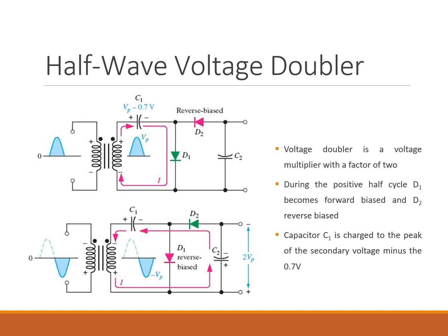Yeah, no transformer is needed. It's ideal for low current, high voltage because we're stepping up the voltage, and there's no way around it. Current has to go down if voltage goes up. It's the law of conservation of power. There's no other way, not in this universe. All right. So again, each half cycle builds up to the output voltage, and then you get 2 times the voltage, but current handling again is limited.